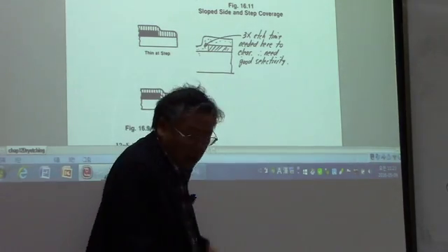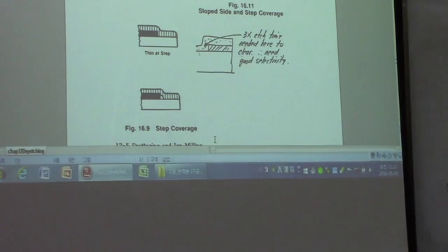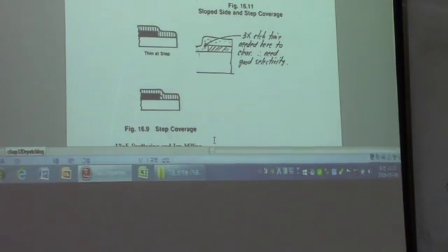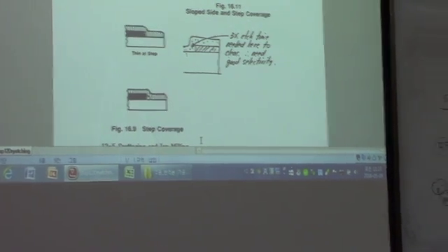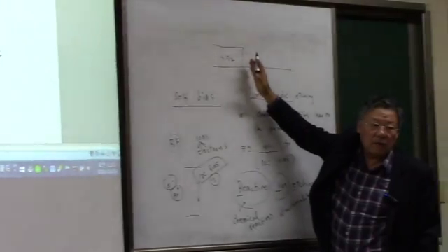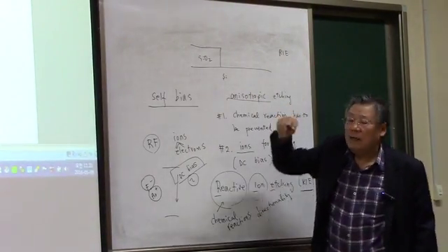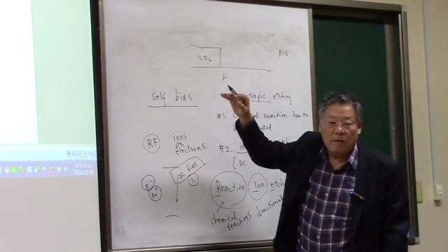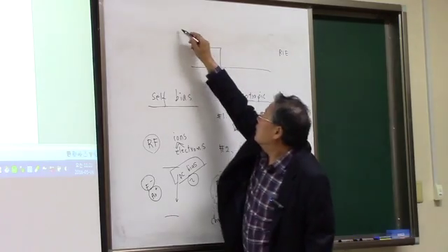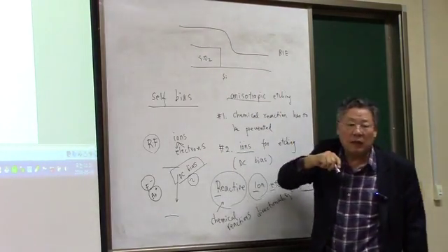Here, if you do the RIE etching, because of this anisotropic nature, you are going to have silicon oxide and silicon, for example. You can have very steep walls after the etching by RIE, okay? And then if you deposit some metals on top of this for the later process, then the metal is going to be deposited something like this.